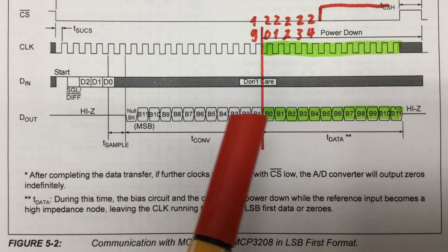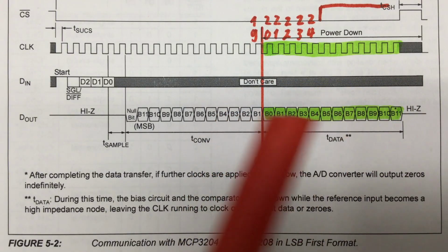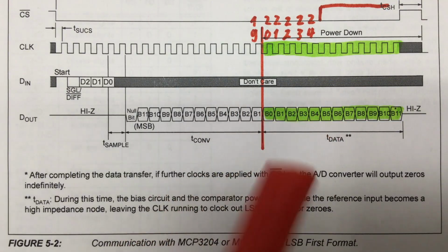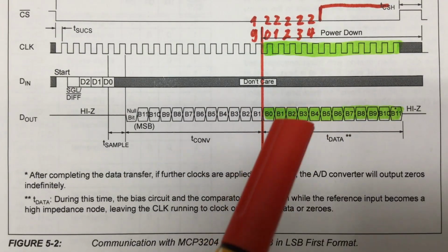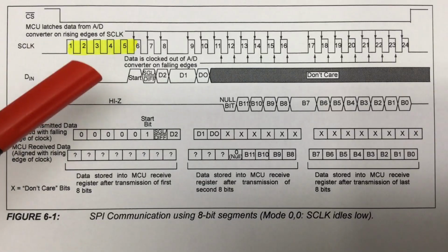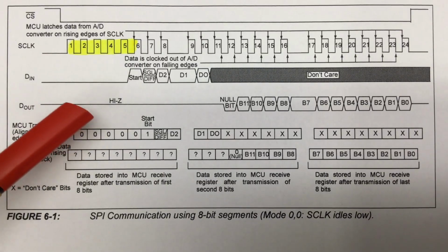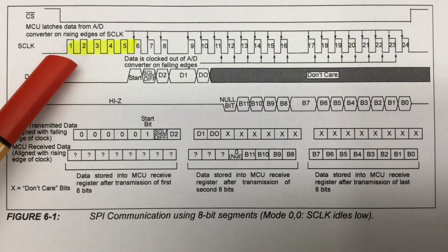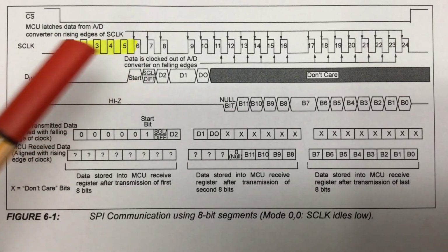All that happens is we shift in the least significant bits first, but we can bit bang that out inside our code. Or we could, like Microchip Technology suggests in their datasheets, add 0 filler bits up front.